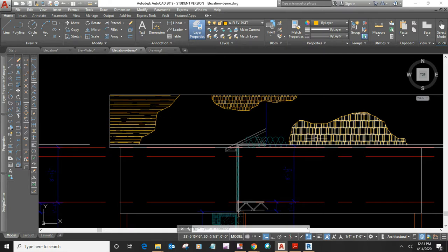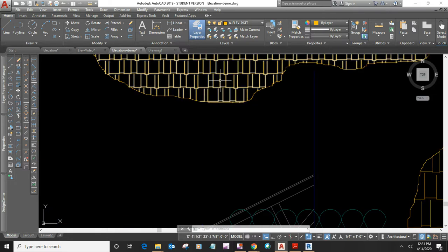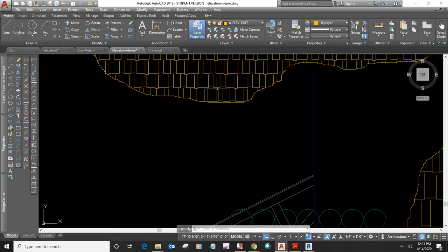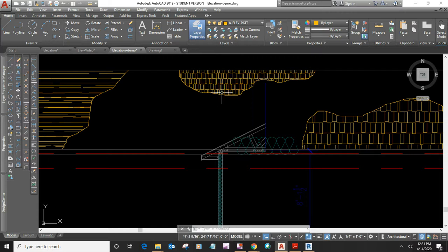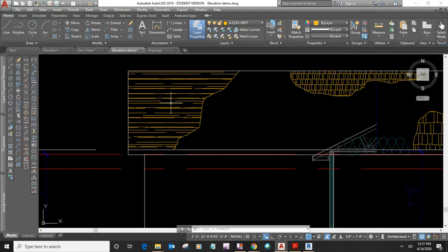The problem with the shake is that it looks vertical. For a wall, that's fine, but for a roof, it is not fine because it looks vertical. The only way to scale these things is to do a generic scale, and I pulled them back down. This one is scaled so that the length of the shakes is about 5 to 6 inches, which would be normal, but that also shrinks the width of it. So really, the roof shake hatch doesn't look too good on an AutoCAD drawing, but this one will.